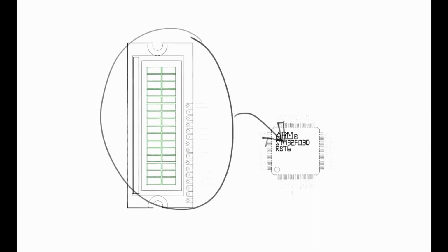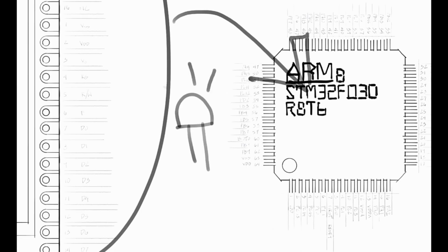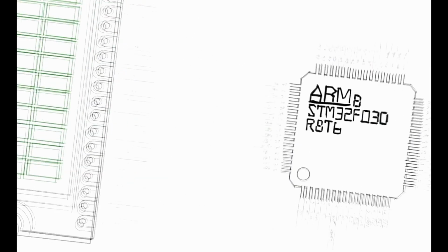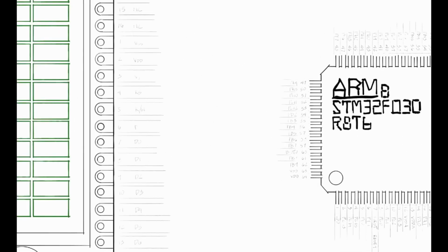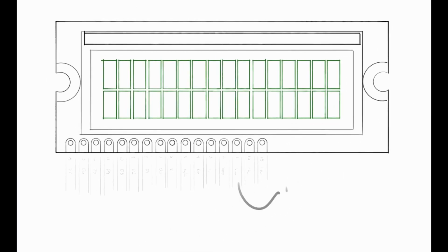We will connect an LCD to the ARM microcontroller. LCD communication is no more complex than lighting up LEDs and testing button presses. The only difference to controlling an LCD is the way we turn on and off a pin and the timings between each bit going towards the LCD. The LCD that I'll be using is of the standard flavor. The LCD is powered by 5 volts. It has 16 characters per line and contains 2 lines.